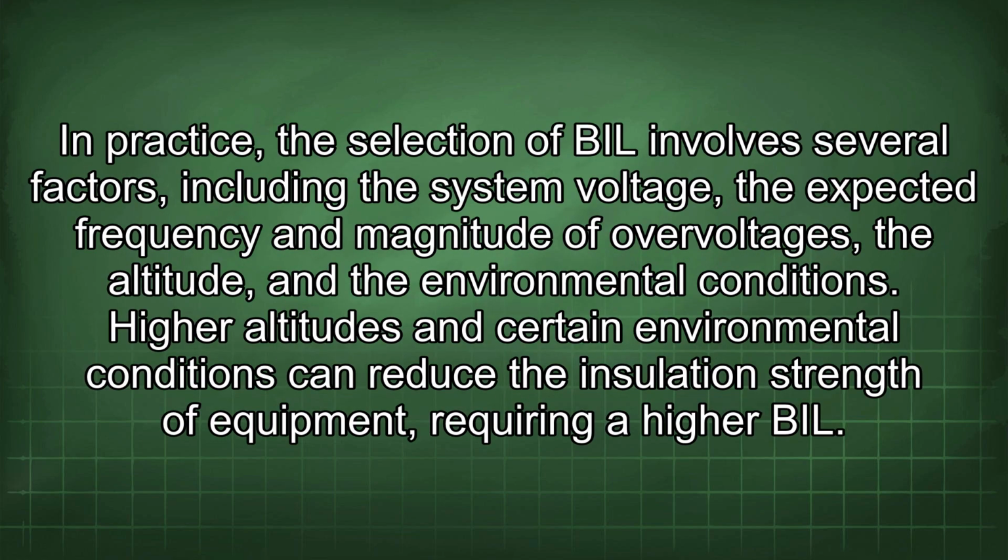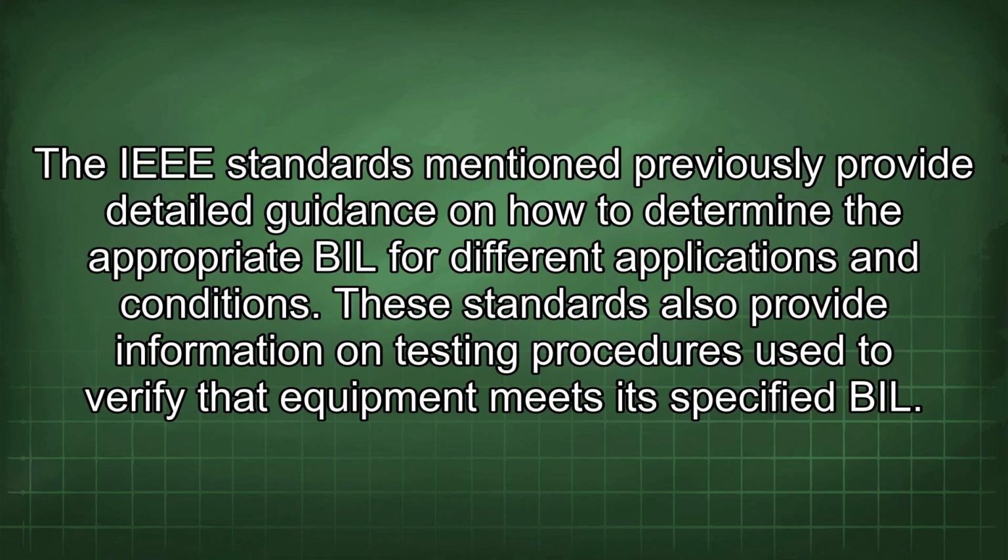In practice, the selection of BIL involves several factors, including the system voltage, the expected frequency and magnitude of overvoltages, the altitude, and the environmental conditions. Higher altitudes and certain environmental conditions can reduce the insulation strength of equipment, requiring a higher BIL. The IEEE standards mentioned previously provide detailed guidance on how to determine the appropriate BIL for different applications and conditions.